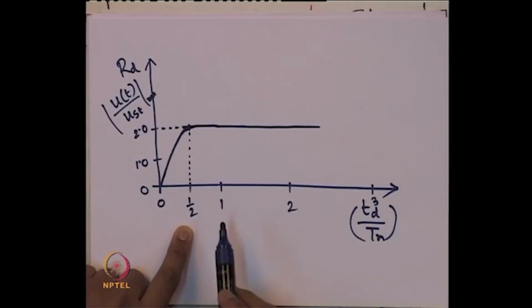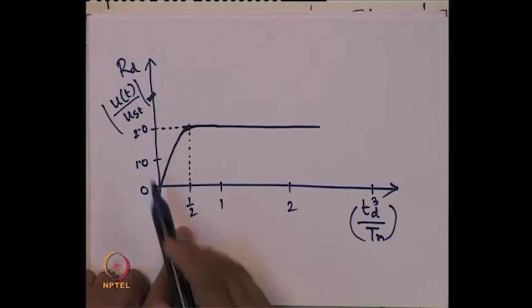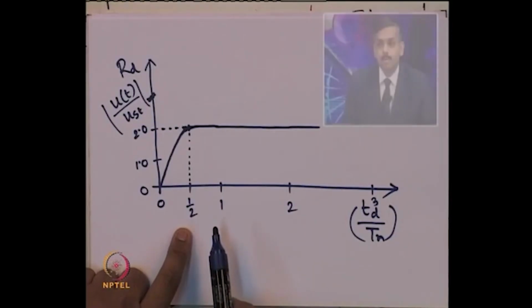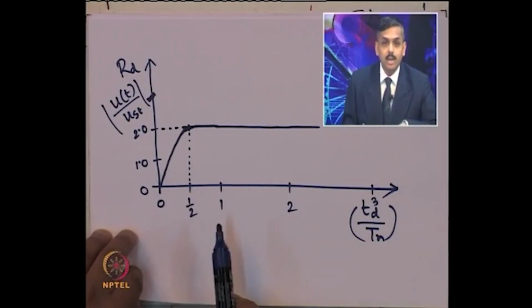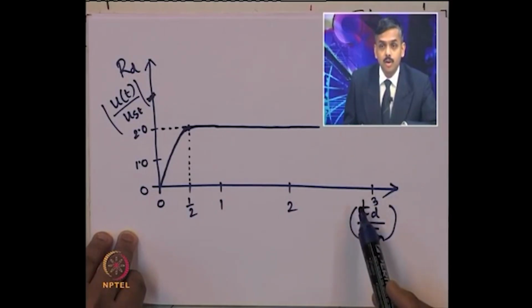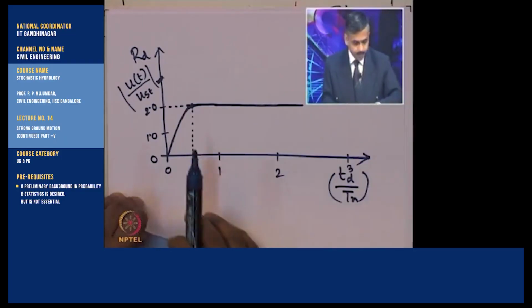But if it is random, a similar process has to be used to get the solution and get this response like this. So, that similar procedure we adopt for the earthquake random motions also, which you have to solve using the Duhamel's integral process, which I have discussed thoroughly in the soil dynamics course, right, for any kind of motion. But everything finally will be a function of how long that earthquake motion is occurring with respect to the natural time period, and at what point of time you are interested to find out the value or response.